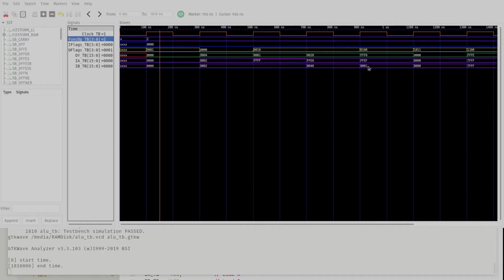In the next one, we purposely add 1 to this, which bumps this up to FFF0. We expect that. We also expect that the negative flag, that's what this bit here, has gone high. And the reason is because one of the operands had the most significant bit set, which gives us a negative value. That's what we expect. Now let's look at another case where we're adding two numbers where only the most significant bits are set, which is 8000. When we add those together, we get 0, but everything rolled off the end here, and that gives us our 0 flag because it's 0, gives us a carry because of the rollover, and it also sets the overflow because these two values overflow.